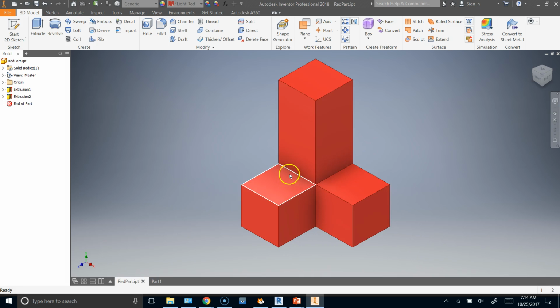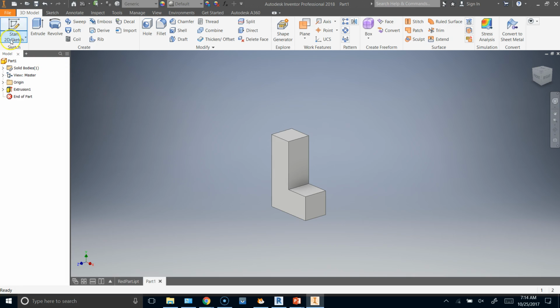The only thing I need to add now is I have this additional cube projecting from the front view, a single cube, 3/4 of an inch deep, 3/4 of an inch wide, 3/4 of an inch high. I'm going to come back to my part and I'm going to draw a new sketch. So all we need for sketches are planes or surfaces of objects. This is not a plane because it's a small surface, but there is a plane that would contain the small surface. So in fact, this surface is merely a representation of a portion of a plane. I can use that to sketch.